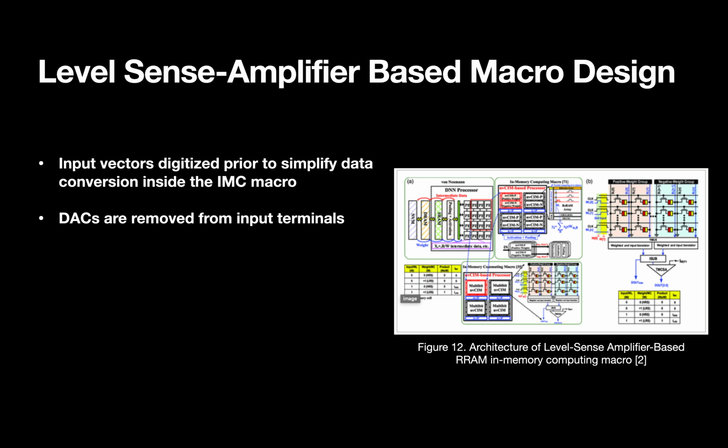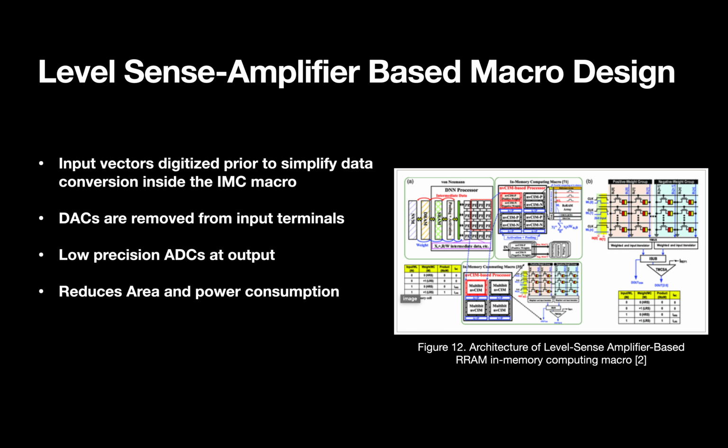The quantization of the conductances lowers the output precision requirement to as little as 4 bits, which will simplify the ADC design. Instead of conventional ADC architectures, low precision ADCs are feasible from multiple binary sensing amplifiers. Such a simplified design scheme without an ADC module reduces the area and power consumption, but introduces increased latency and operation overhead.